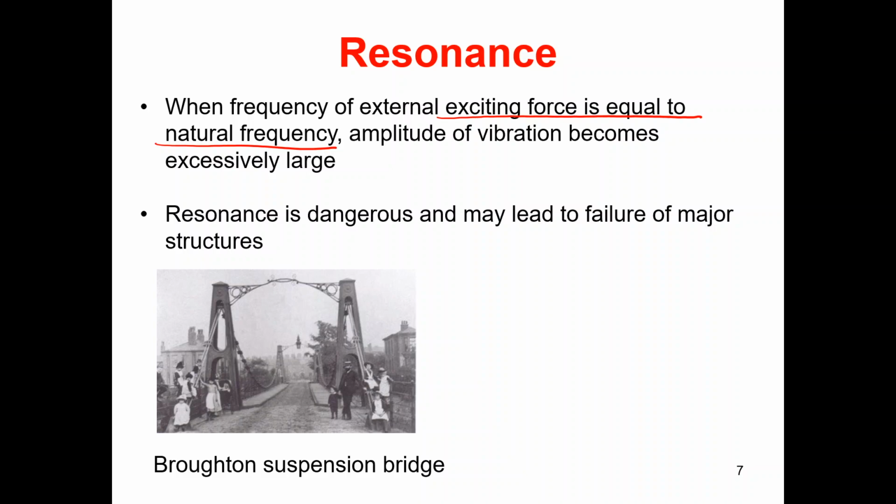What happened was, when they opened the bridge, one day soldiers were marching on it, and the natural frequency of the bridge became very close to the frequency of the soldiers marching on the bridge. So a very dangerous resonance happened and essentially caused the failure of the bridge.